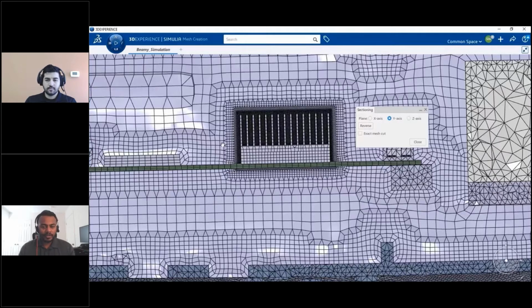Now, the open areas within this boxy enclosure, we might not need a very dense mesh, and we could probably have a much coarser mesh, right? Well, the meshing tools enable us to very easily specify all these different meshing criteria, and we can even mix different meshing as well.